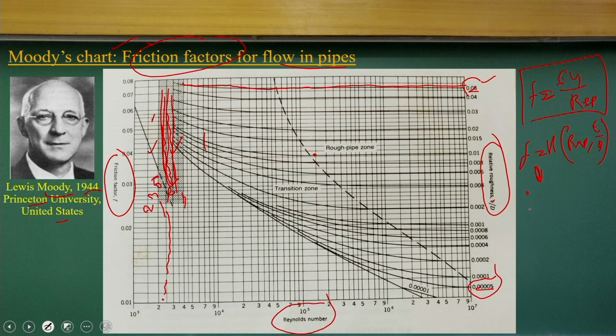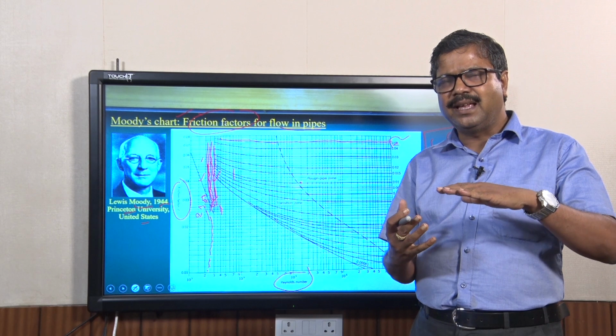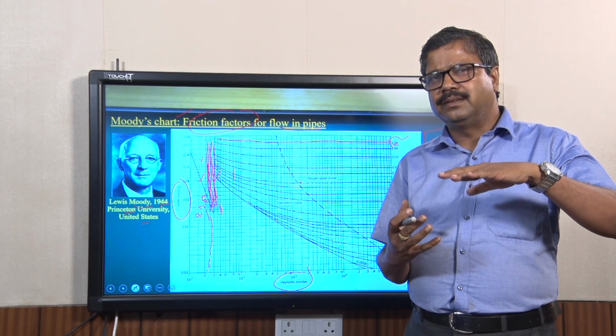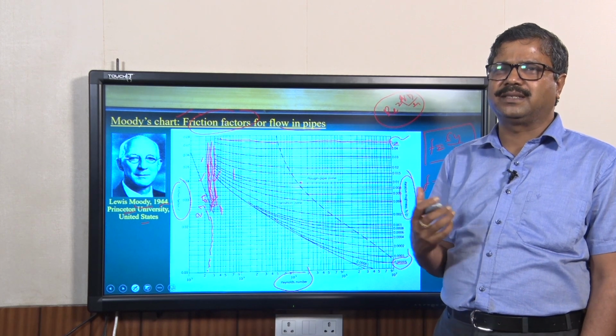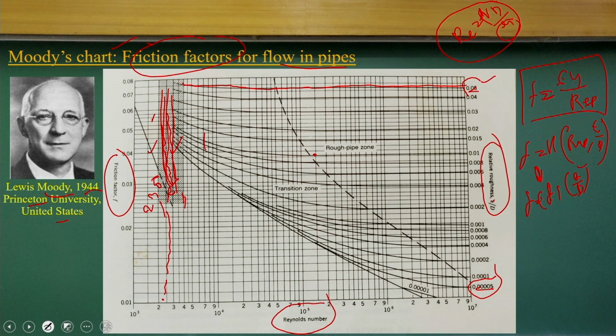That means after that the friction factor is a function only of the relative roughness; it does not depend upon the Reynolds number. Now, physics wise, what happens is, as we increase the roughness, the Reynolds number, which represents V d rho by mu, does not have much significance; the viscous effects are not significant, and more the effect of the roughness comes in. The mu component has not much significance, as you go to more roughness, it becomes independent of the Reynolds number. That is the reason it is constant, independent of the Reynolds number, and just depends upon the roughness values.